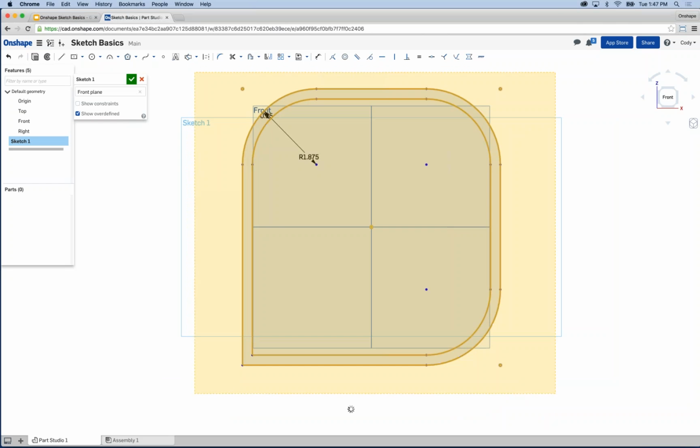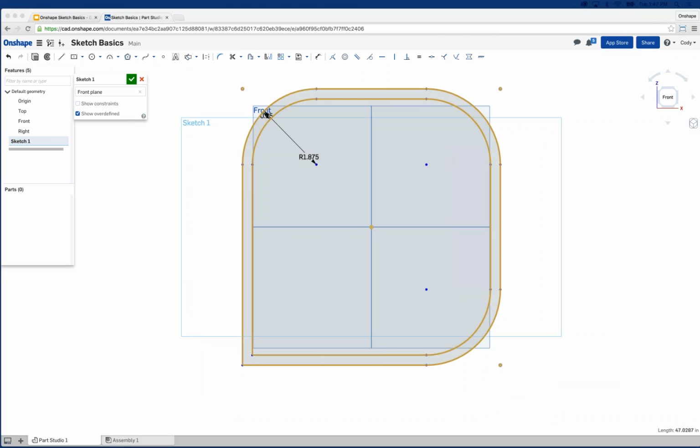Okay? And also, by the way, sketch fillets. A question: I'm never sure whether to fillet in sketches or on 3D extrusions. Do you have guidance on this, please? In general, this is something that you'll find some people argue about, even amongst experienced CAD users: should you create a fillet at the sketch level, or should you create it at the 3D level, in the feature level? And the answer I often give is, if you have an edge that's filleted the same radius in several places, I would often do a feature level fillet. It allows me to click a fillet and click on several edges and have them all tied together.